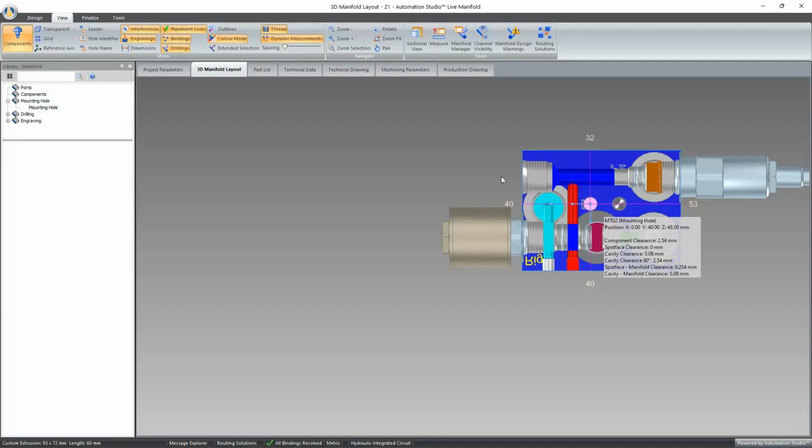Now I'm not respecting the options that I've set, so my clearance isn't enough. You can see that if I highlight it in the tooltip, it says the current clearance does not respect the current drilling clearance rule. So we can see that I can go back and adjust it to 42 once again.